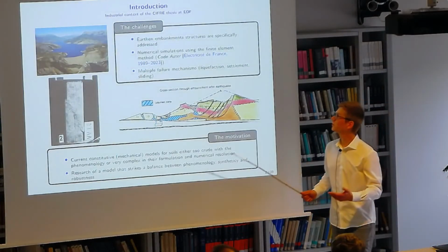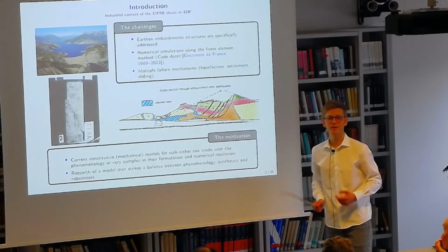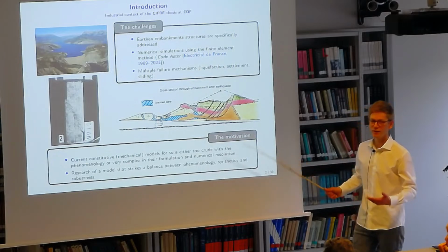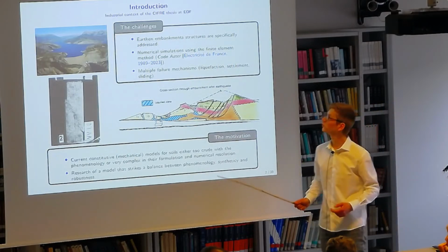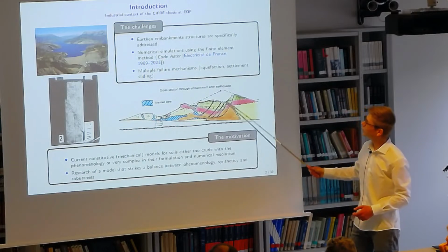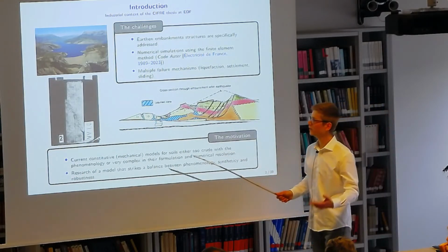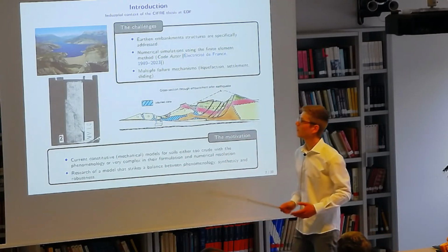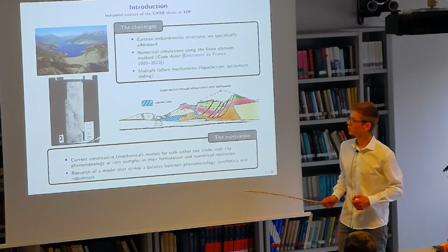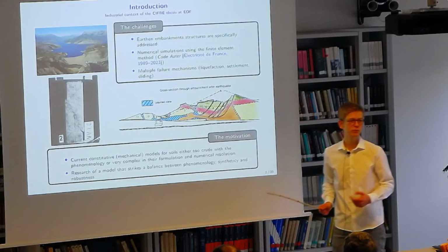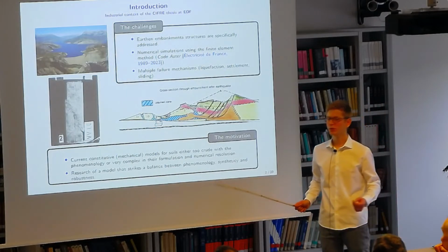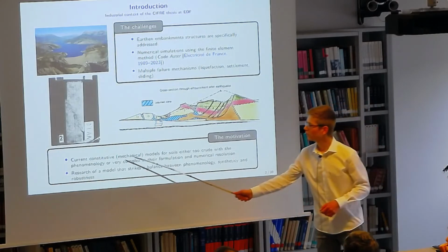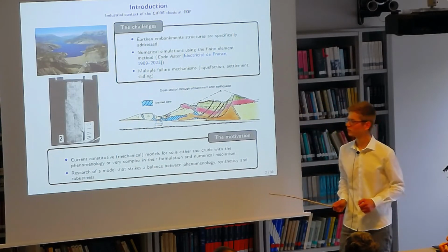To start this presentation, I would like to position this thesis at Électricité de France, in which we aim to study some infrastructures like dams or dikes, which are concerned with mechanisms of failure like liquefaction, settlement, and sliding, which can also, on the other hand, be observed in the laboratory with experiments on granular soils. The methodology used in order to predict and thereafter to avoid these mechanisms of collapse is to carry out numerical simulation with the finite element method, which needs a constitutive model to describe the phenomenology of granular soils.